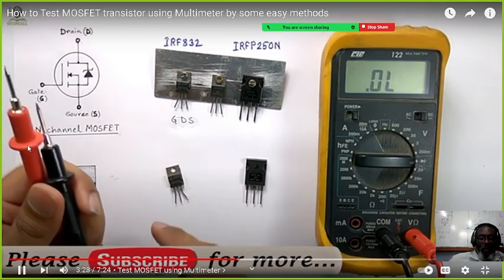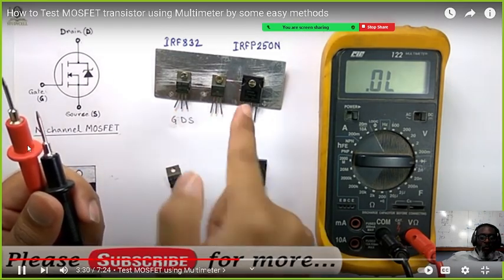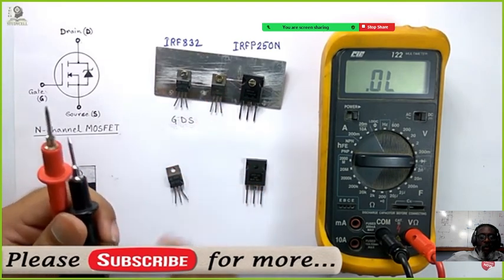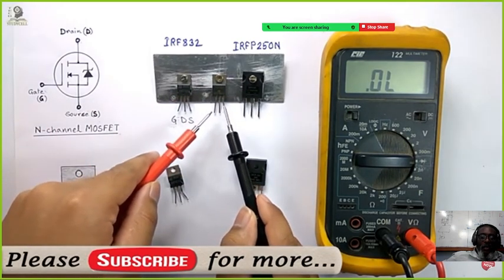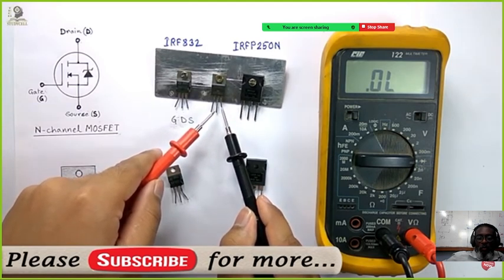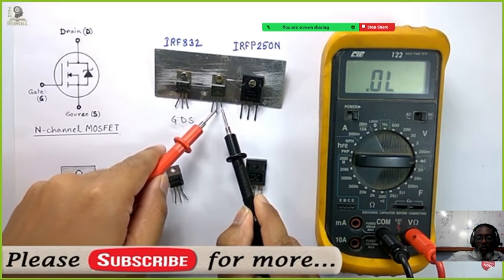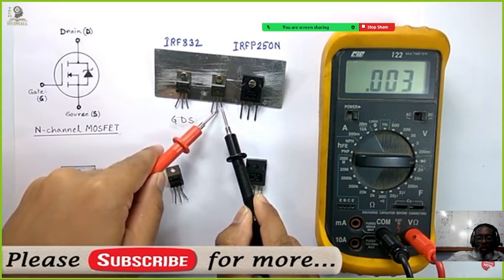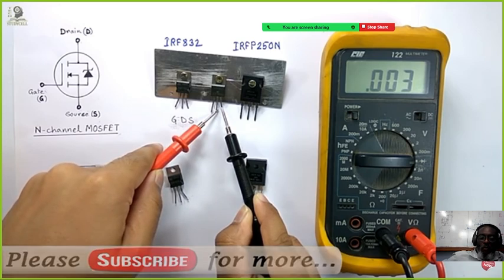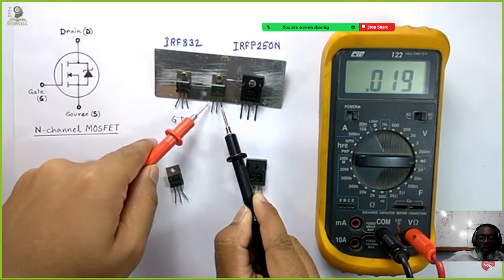MOSFET, how to check it? First you have to discharge the three terminals with your finger. So we're gonna check this one, and if this procedure is followed, we're gonna check if this one is good. Connect the source with the black lead and the drain terminal with the red lead. You're not supposed to get any continuity for a good MOSFET, but as you can see, I'm getting continuity. That means there is a problem in this MOSFET. You're not supposed to get that.